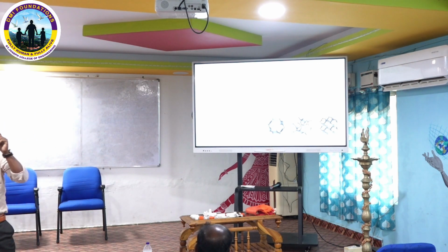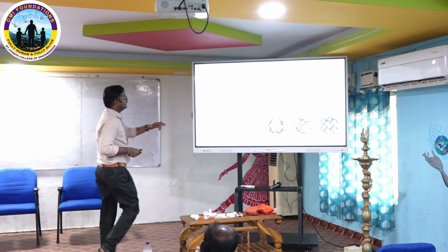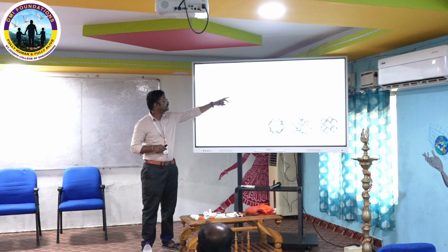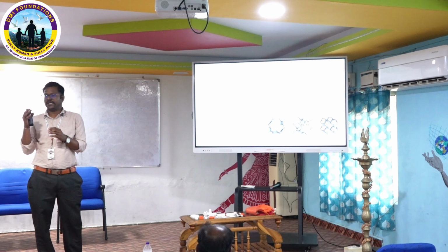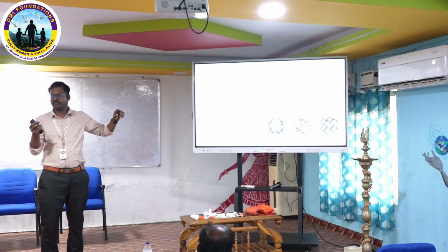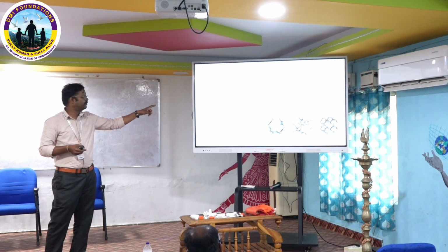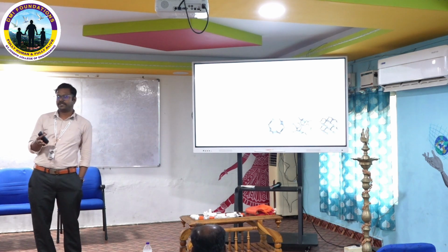It is the 2D representation of a lattice structure or unit cell, which explains how lattice structures have struts and nodes. Here, in the equation, S is the number of struts. N is the number of nodes, the junction point of two struts. So if you select any unit cell, you count the number of struts and nodes, apply this equation and get the value M, the Maxwell index. Below 0 means it is a bending dominated structure.